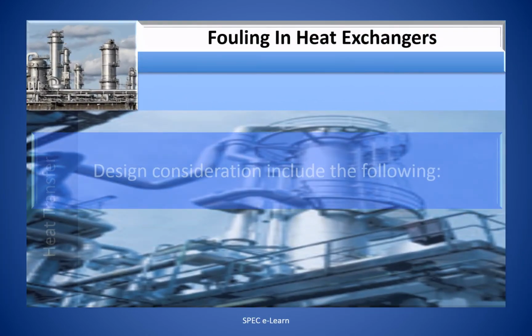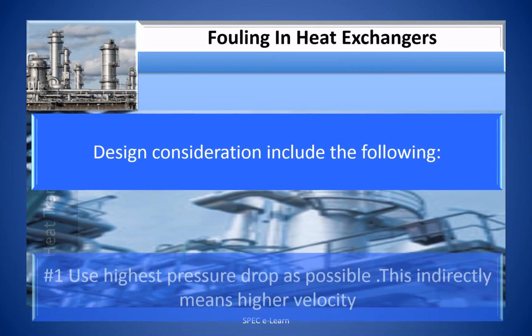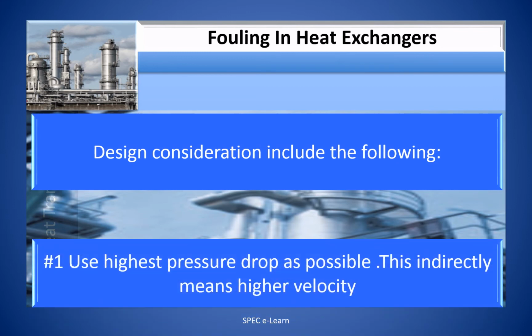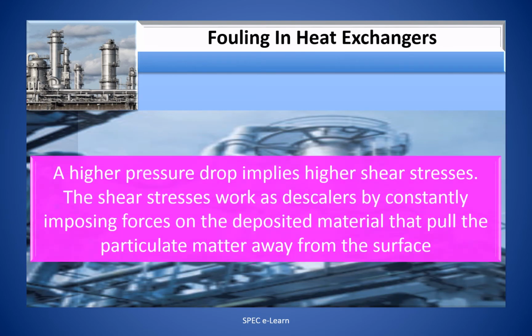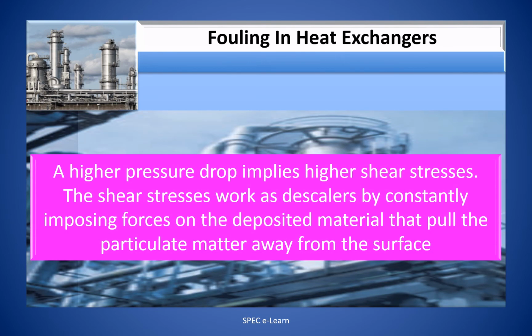Design considerations include the following. 1. Use highest pressure drop as possible. This indirectly means high velocity. A high pressure drop implies higher shear stress. The shear stress works as a descaler by constantly imposing forces on the deposited material that pull the particulate matter away from the surface.